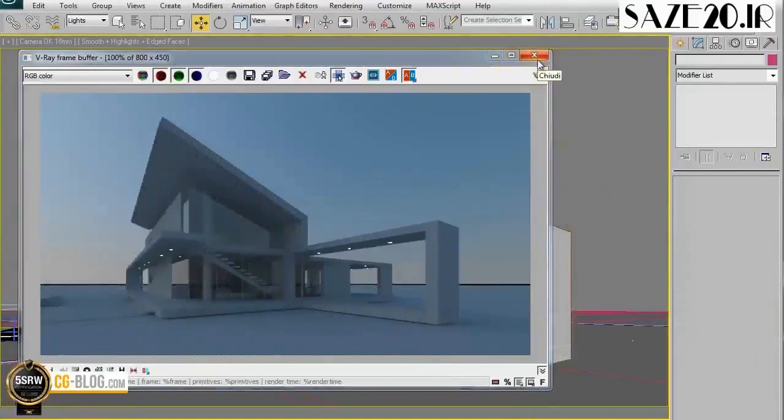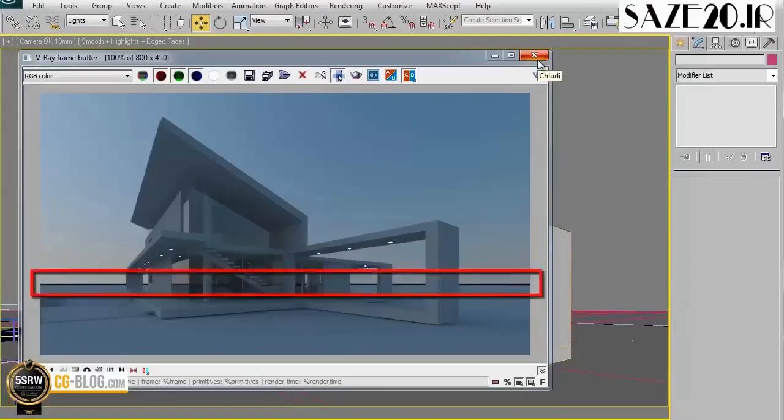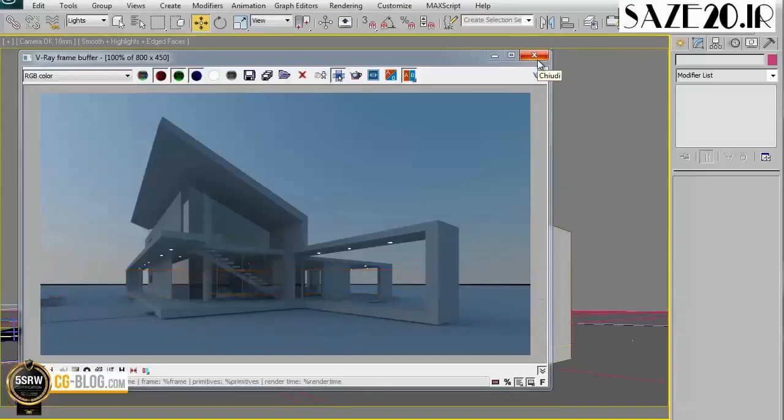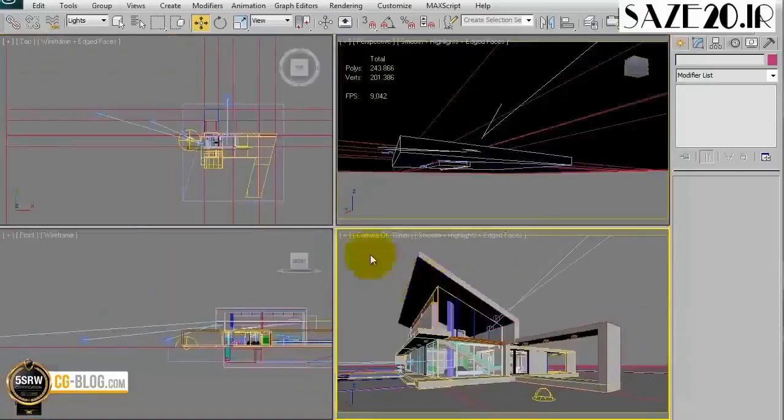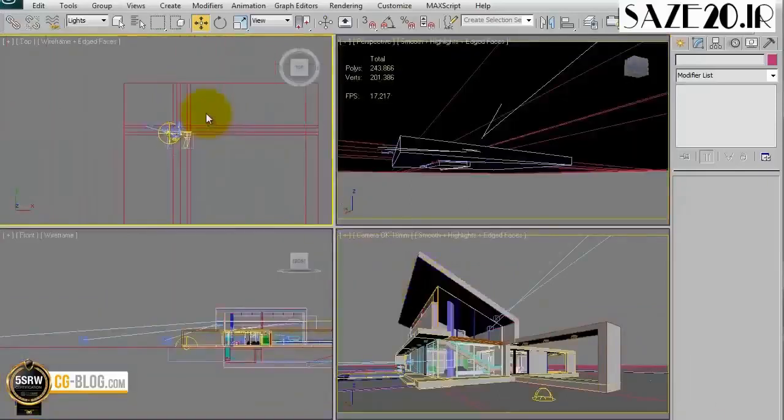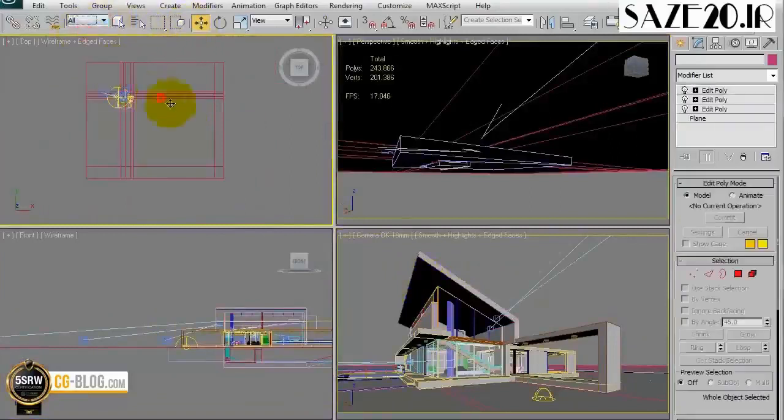When using V-Ray dome light, we can easily get some strange effect on the horizon, a black line and sometimes a white line. The problem is that the object ground does not cover the surface to the horizon. A very simple way to solve this problem is to raise the floor in the distance, as a small hill.